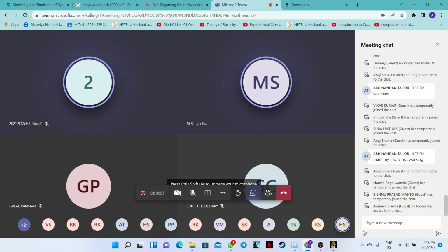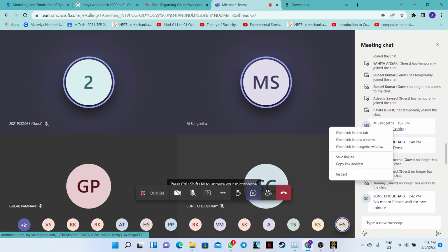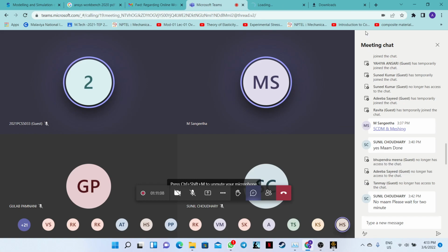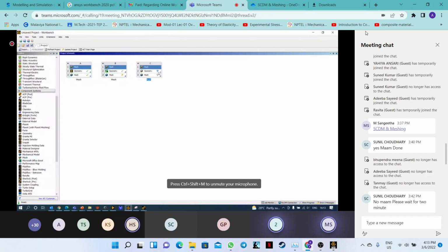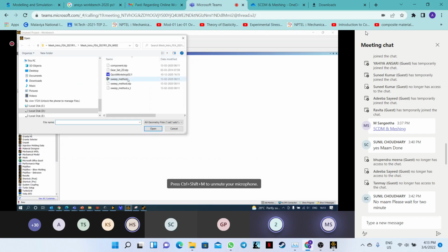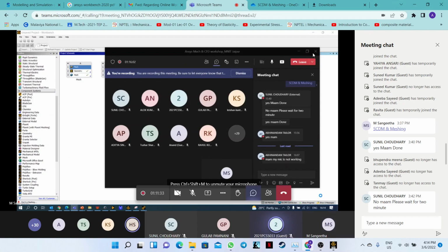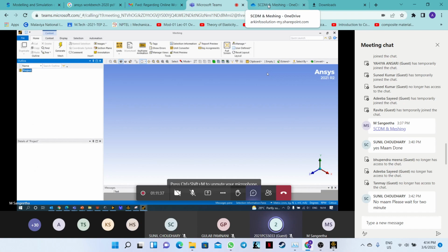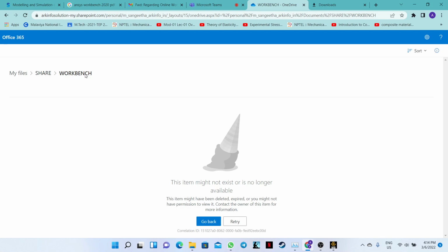Okay, so the workshop name is quick workshop, and it's an AGDB file. So just follow the same procedure to import your geometry. Go to mesh, geometry, and then you have browse. So whichever is your geometry, open it and then start working. Okay, so this is your geometry.